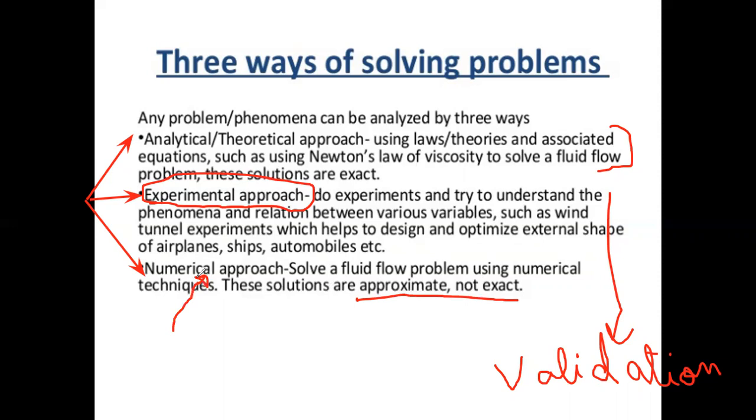When we say parametric study, this means that we identify the main parameters of the problem. For example, for an HVAC application, the main parameters will be the supply temperature, the supply velocity, the heat fluxes within the space, and the heat sources in the space. I can vary these and see how they affect the flow pattern and the temperature profile. Then I can conduct several simulations in CFD. This is what we call a parametric study, which assesses the effect of each parameter on my output.